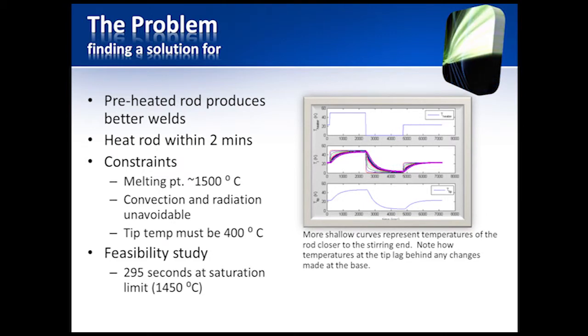And in order to check to see if this is even possible, we did a feasibility study and we started heating the rod at 1450, so full bore. 295 seconds later, the bottom of the rod reached the 400 degrees Celsius point. But we also found that we had dead time in our process because in 2 minutes of heating, the bottom of the rod was still room temperature, and so the dead time was longer than 2 minutes, and we had to work with that.